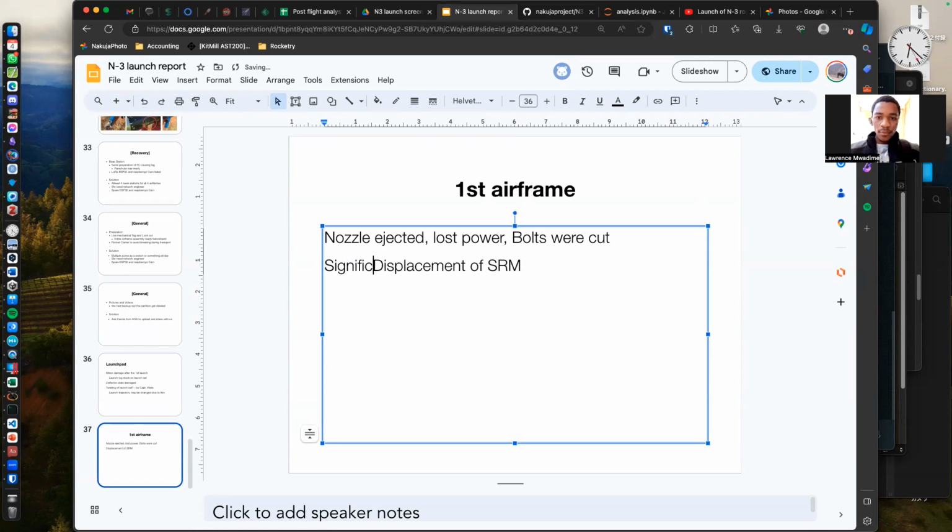But it was worrying for me because logically speaking, the motor and the airframe are going in the same direction, so there shouldn't be that much damage. The only reason for that amount of shear on the skin would have been if there was resistance on the rocket from the top, which was quite a concern after the first launch because we had the lug stuck and it could not move. So we thought that the resistance of the lug is what had caused the motor to try and push into the rocket, and that's what caused the tear on the skin of the airframe.